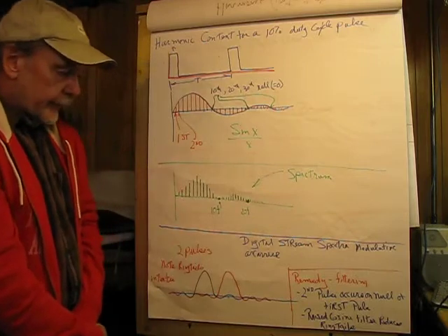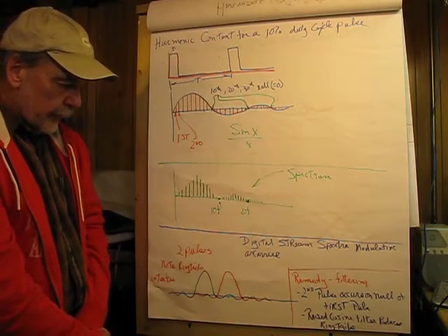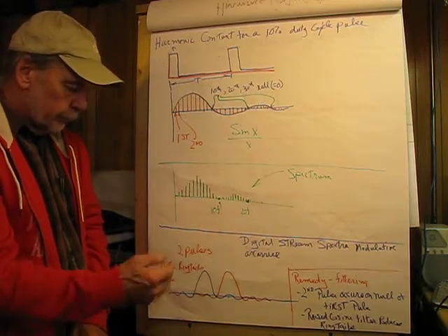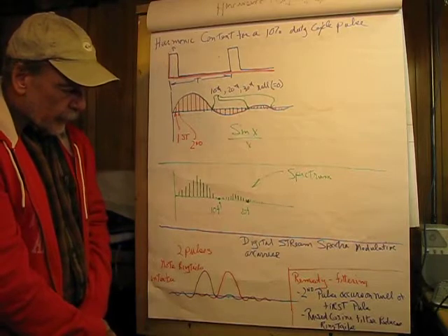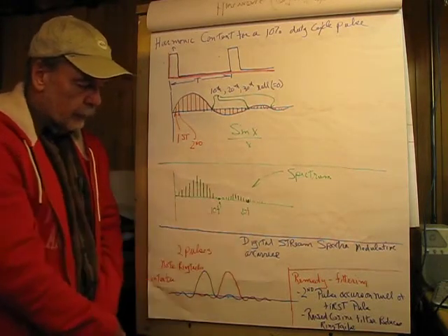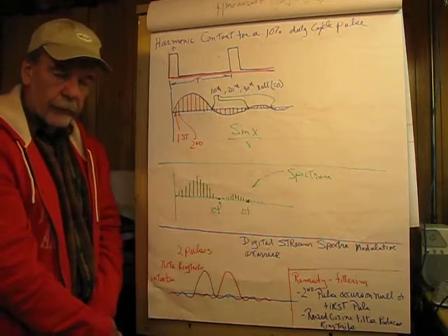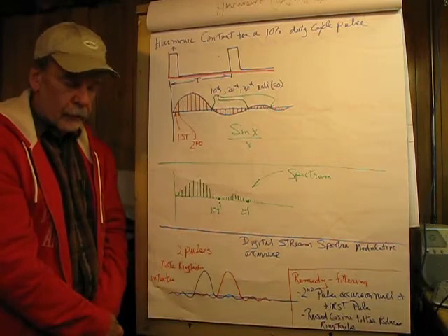Now let's take a look at some of the things that can happen here. Suppose we have a digital stream, and we're going to, say, modulate a carrier or something like that. And what happens now, as you can kind of see, is that these tails from this here are capable of interfering with the next pulse, or lack of pulse, could be a zero.